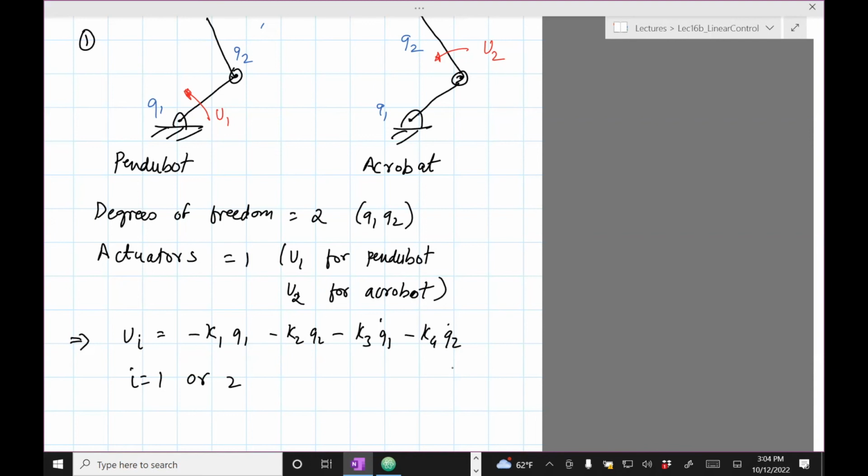It turns out that what you can do here is linearize the system, just like I did in the equations, and then use an LQR controller to control the system. The gains which come out are very non-intuitive. You have no idea why those gains came, except that there's this calculation. It's kind of like magic that it works. If you look at videos online, you'll see people doing it. They probably use some manifestation of pole placement or LQR. LQR is more popular.